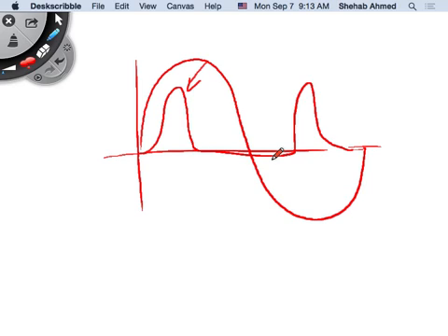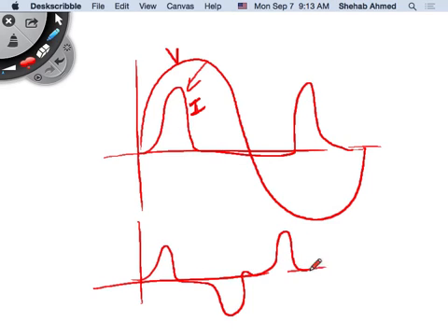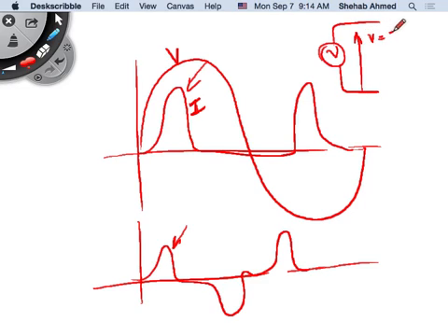If the load is nonlinear, then it's going to respond somehow. This somehow will contribute to nonlinear current. So if this is a V, you will supply it with a nice sinusoidal voltage at 50 hertz. It will consume current that looks like this, or current that looks like this, right? This is not the response of a linear load. It's a response of a nonlinear load. So in this case, what do I have? My source is now generating what? A voltage that is 50 hertz, right?